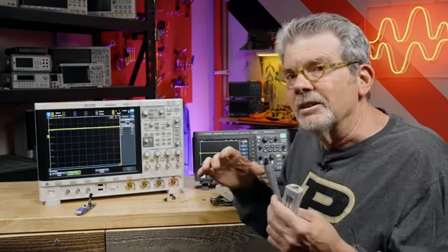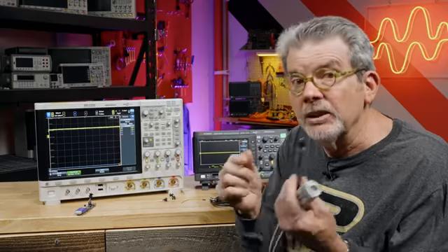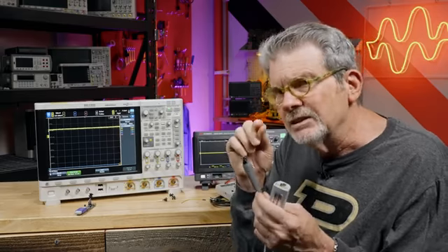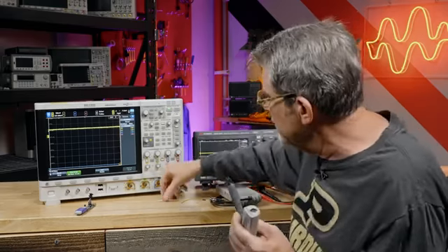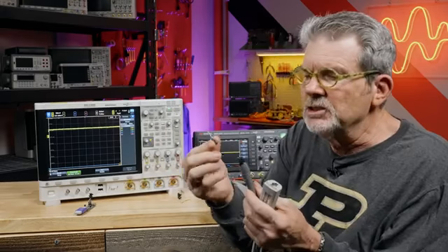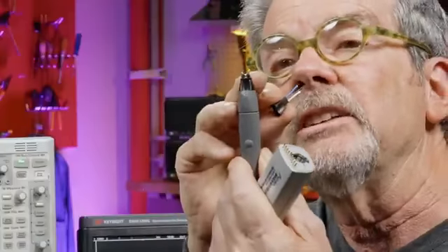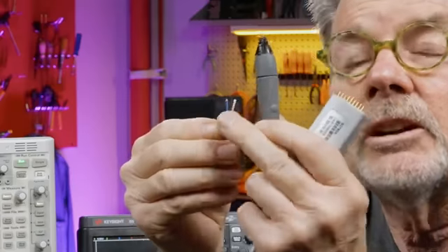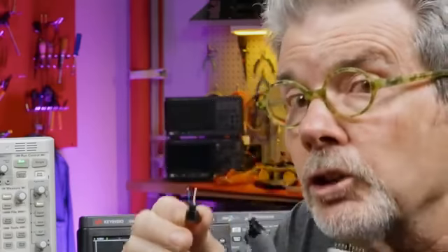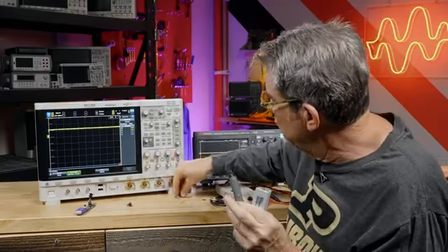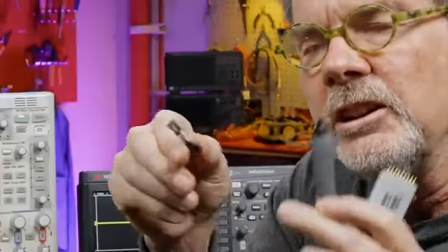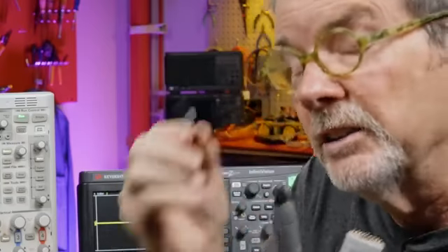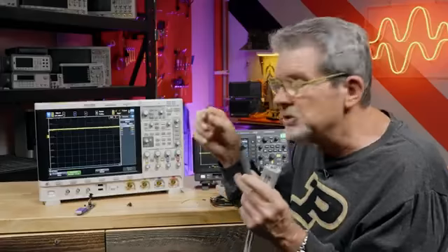Now, oscilloscope vendors typically provide some accessories to help you with the usability. Here's a couple of them I have here. This is a tip that I can replace, and you probably can't see it, 2 very short tips. Very difficult to probe. You can replace it with this tip that has a couple of short wires coming out that you can solder on to the board. Then you can take your hands off. And this one here has sockets, so you can plug it into a header connector. And that's what I'm going to use in just a minute.